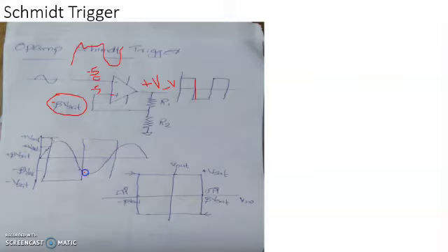For this kind of a waveform, the output will then definitely be a square wave, since it's a symmetrical sinusoidal oscillation. So if the oscillation is sinusoidal but it has some ripples or kinks in the positive and negative peak, it can be converted into a square wave using this circuit.